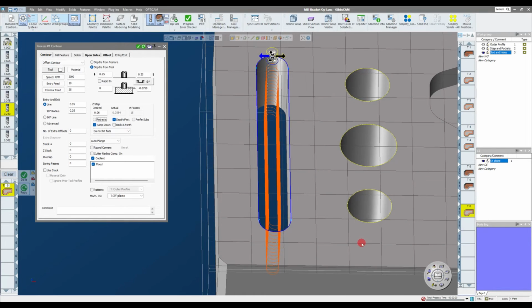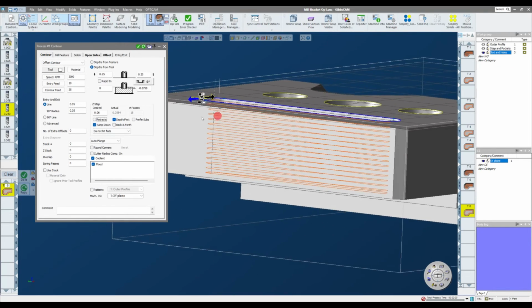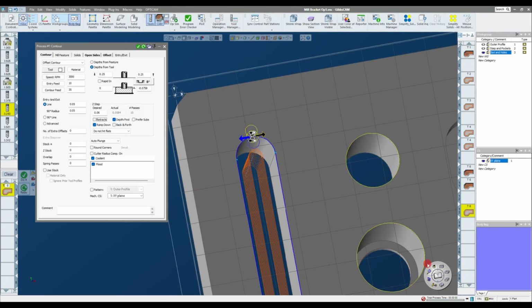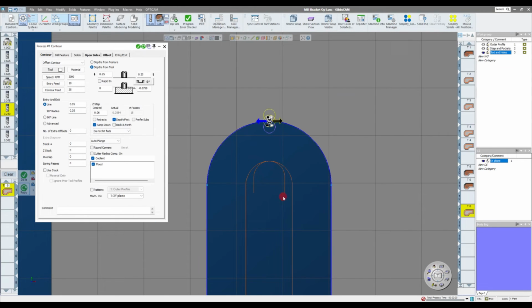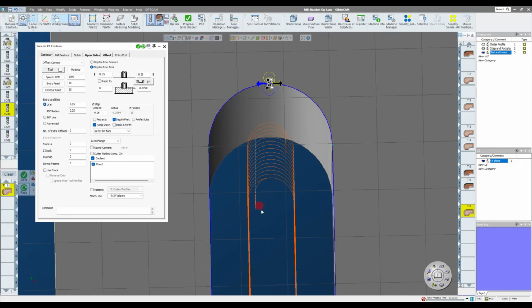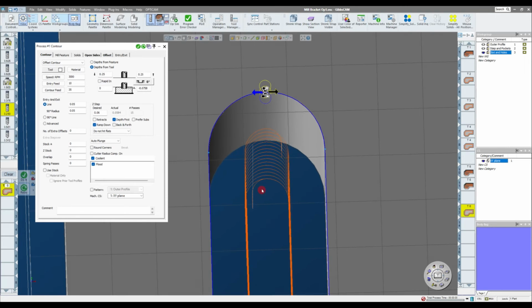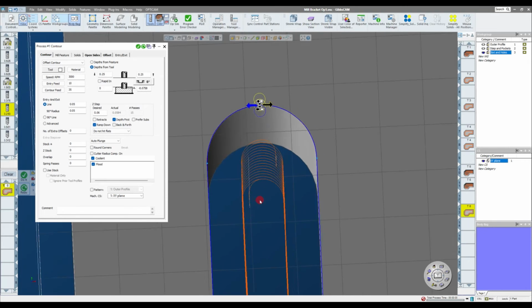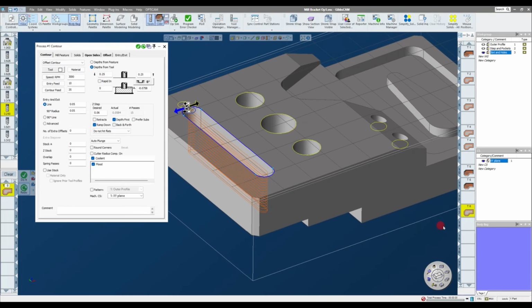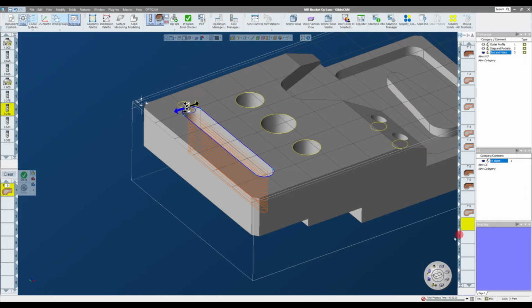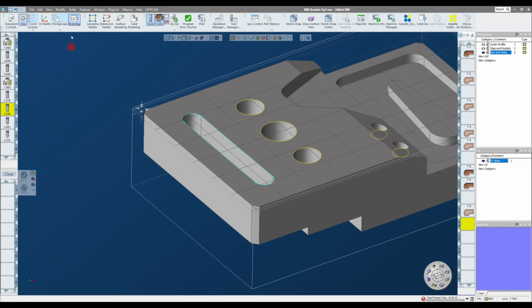All right. So I have a nice ramp down cut. Now if I look in the top view, the lead in and lead out starts at the top, and on the bottom the cut ends up down there, nice and clear. So I'm happy with that. All right. So once I'm done, deselect on the right, clear on the left. I'm going to go File, Save.